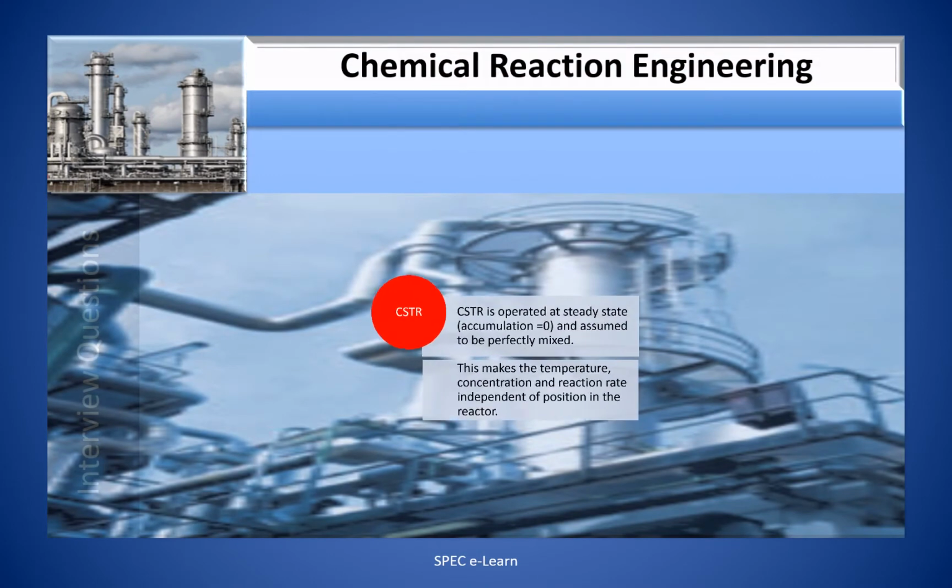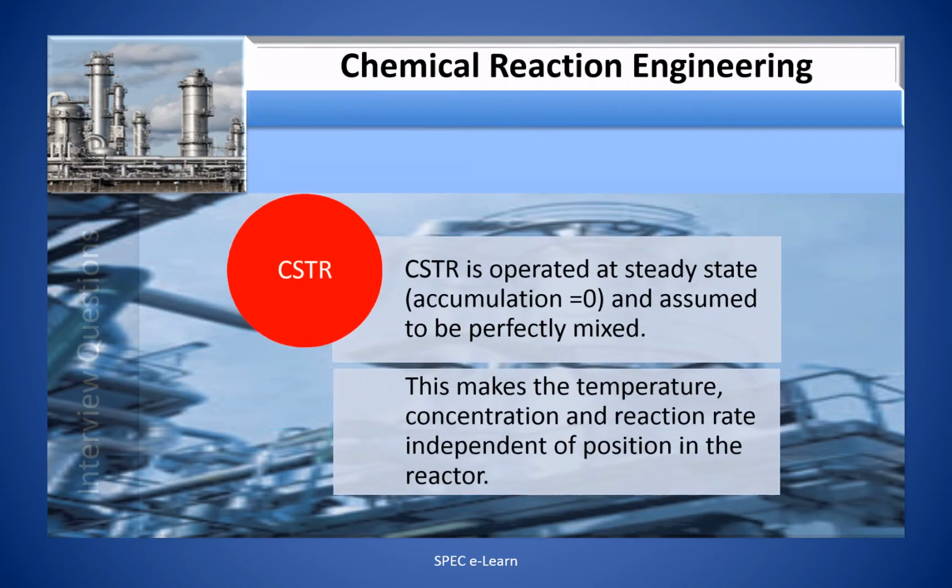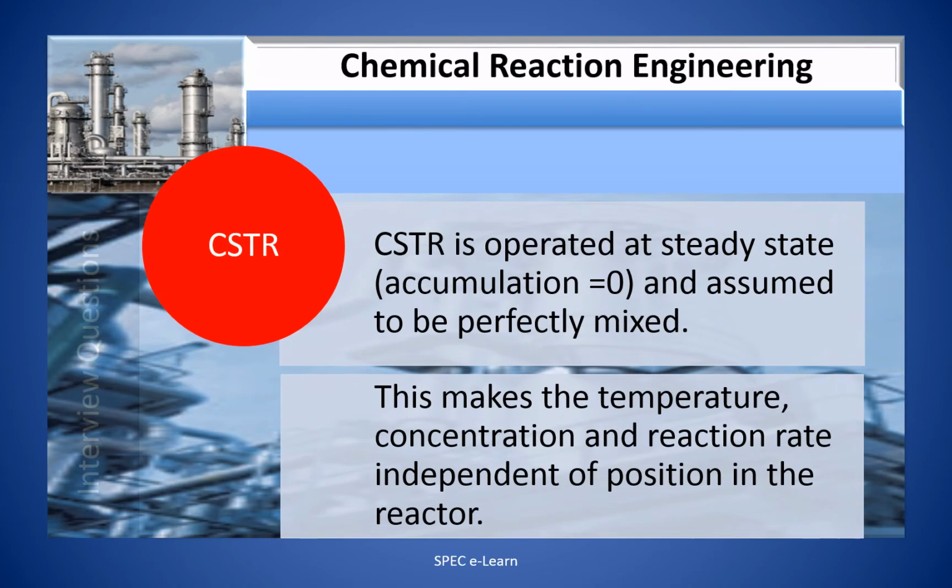A CSTR is operated at steady state, meaning accumulation is zero, and is assumed to be perfectly mixed. This makes the temperature, concentration and reaction rate independent of position in the reactor.